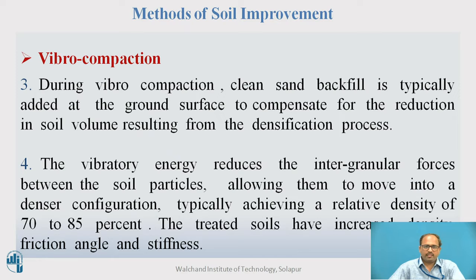Your soil is converting into denser soil. You typically achieve a relative density of minimum 70 to 85%. The treated soil has increased relative density, friction angle and stiffness.